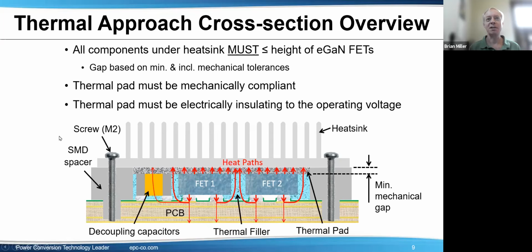This whole presentation today is kind of based around the concept of basically DC power coming out of the FETs. But yes, contact us definitely for those kind of questions, or the back of the data sheets for the initial curves to help that. And there are thermal models with capacitors. All these models here we're showing show resistors to model the current. There's other models we have for each FET, and they're on our website, and we'd be glad to help you find those, that show resistors and capacitors. So like an AC kind of current, a thermal model that we build up, and you can then use in your simulation program to do that kind of work.